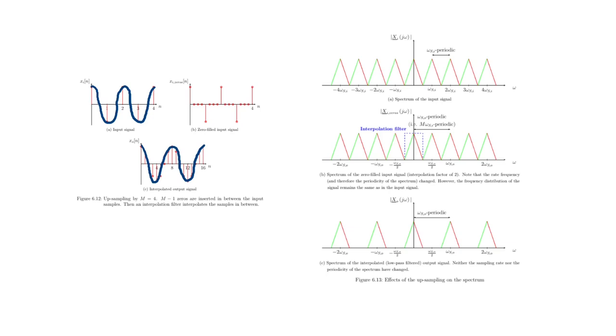But in analogy to chapter 4, where we have considered reconstruction of analog signals, the reconstruction does not give us our original signal back. So the process of decimation or downsampling is always lossy. In this case, we can reconstruct the signal because we had a special precondition. The Shannon-Nyquist theorem was fulfilled for the input signal. And so we can reconstruct the original signal, or a signal which is very close to the original signal.